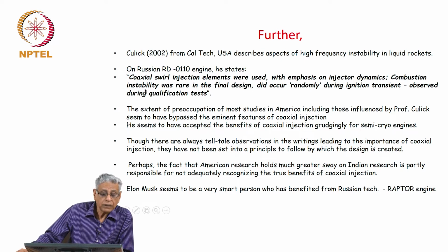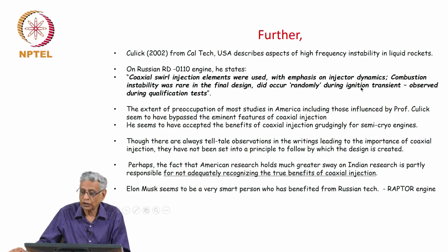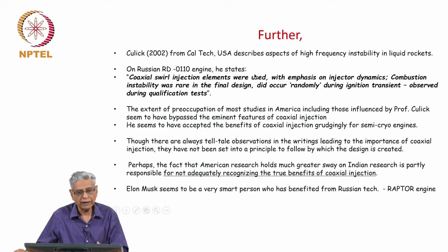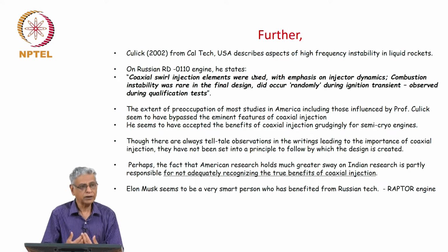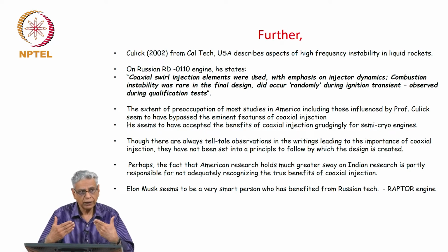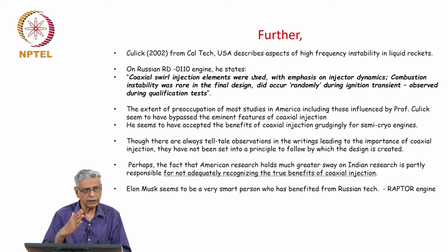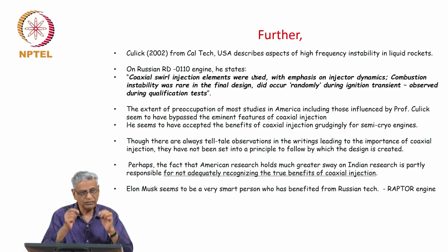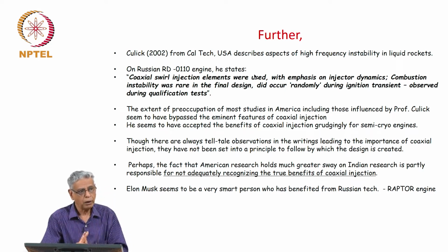The combustion instability was rare in the final design, but did occur randomly during the ignition transient, observed during the qualification tests. Now, this is in fact an argument made saying that they also used to provide baffles, but they provided the baffles in an interesting way. They just introduced the oxidizer posts or the injection holes into the combustion chamber in specific directions so that you have essentially baffles created.